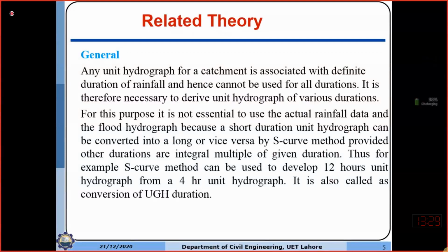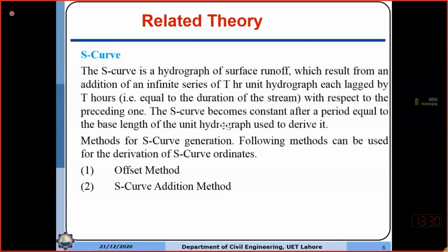also be used to convert the duration of a unit hydrograph to other than an integer multiple. For example, a 4 hour unit hydrograph can be converted to a 2 hour unit hydrograph. T hour unit hydrograph, 6 hour, whatever is the duration. So it is obtained by